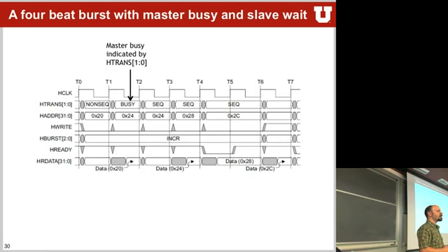Could be. But what can the peripheral now do, knowing that we are in an incremental burst? Set itself up for the next read. Yeah, you can do optimizations in your peripheral. For example, if we know the size of our read, we could go and get bigger chunks out of flash memory. Or if we have to access an external bus system, we can go and get bigger chunks from there to optimize the bus transfers. And that's all what bursts are actually used for.